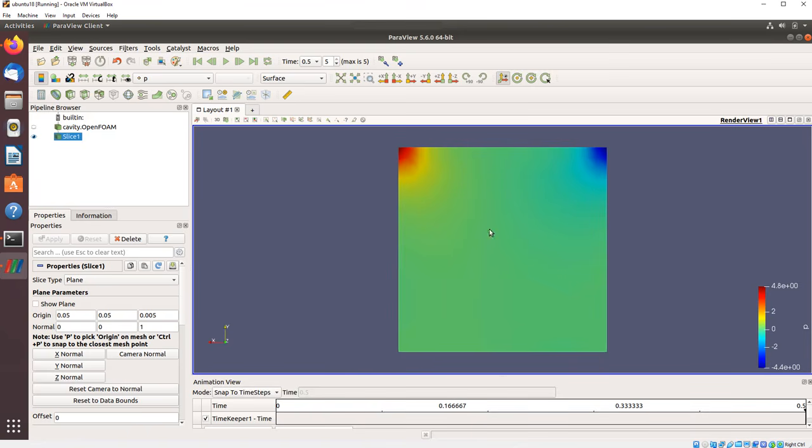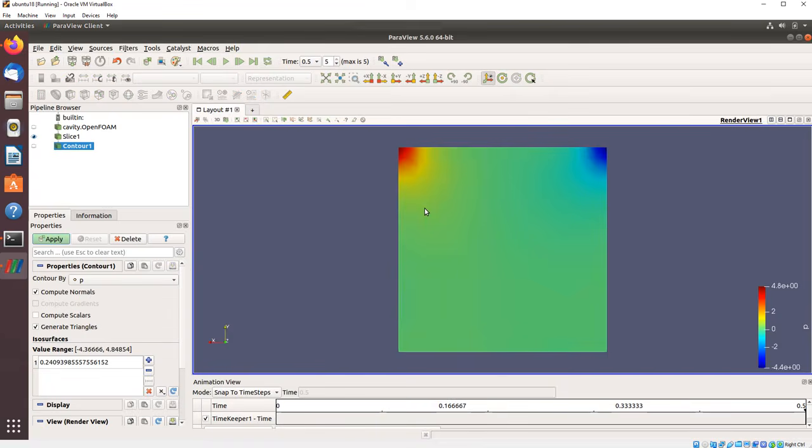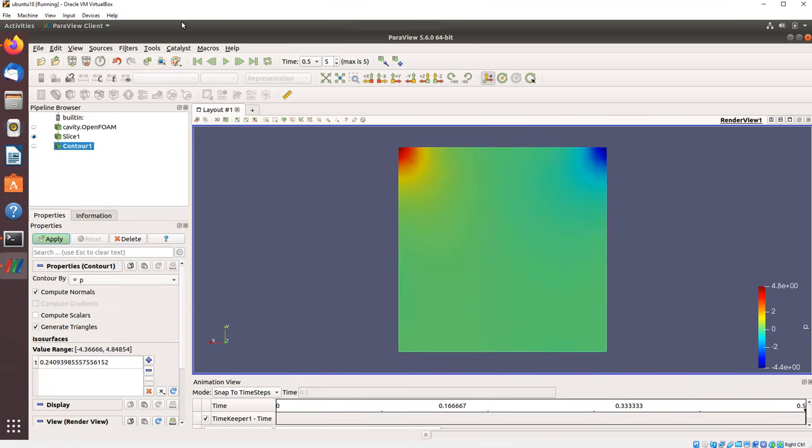And the way to extract this is to use another filter called the contour filter. So I could go again into the filters and search where is this contour filter. Another way to get the filters is to press Control plus space on your keyboard. You'll see this appearing, and then you type contour, you search for the right filter, and you apply the filter by pressing enter. So that's much faster. So you have to remember Control plus space to do this. It's the same as going into the tools, but it's much faster.